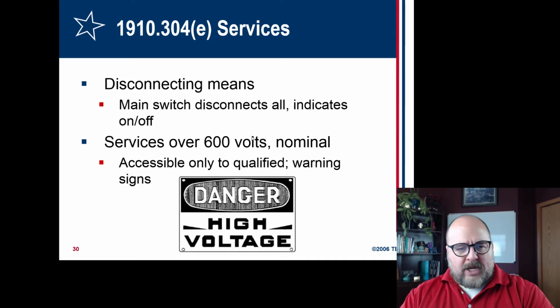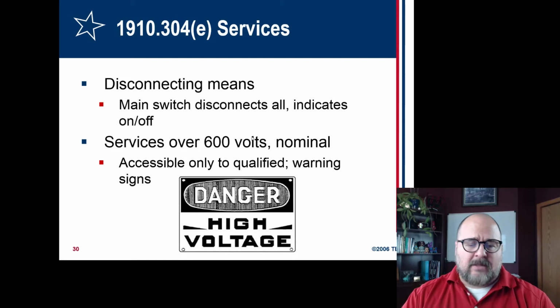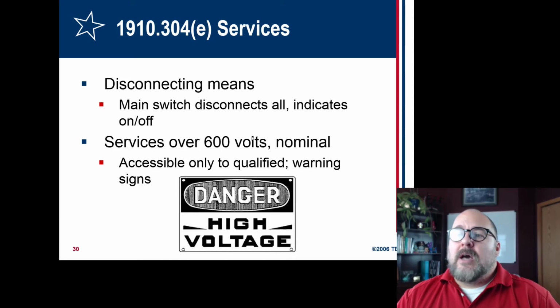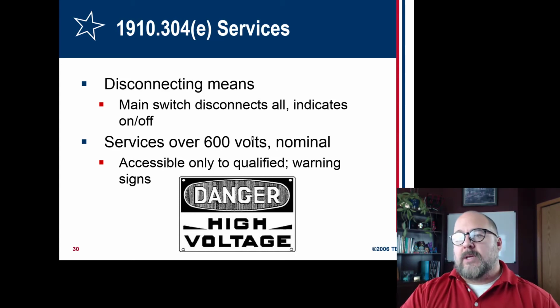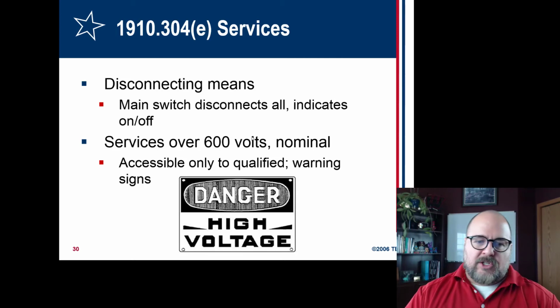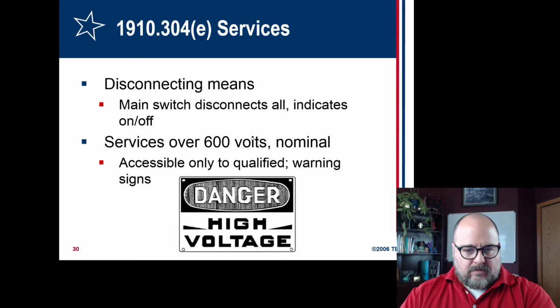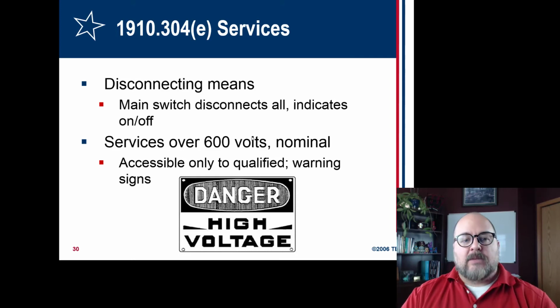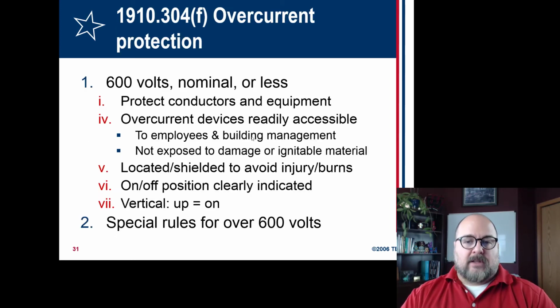You have to make sure that there is disconnecting means. So in a home, that's the circuit breaker. In businesses, there could be a sub panel or something that has just a switch. It just depends. But anything above 600 volts needs to be properly labeled, contained, and protected, because that'll definitely kill you. The other stuff could. 600 volts will kill you.